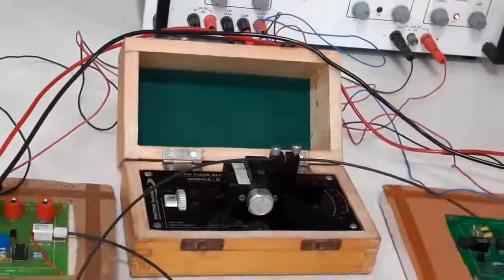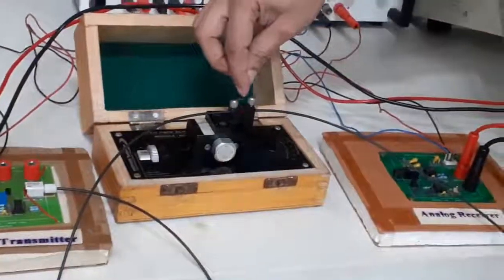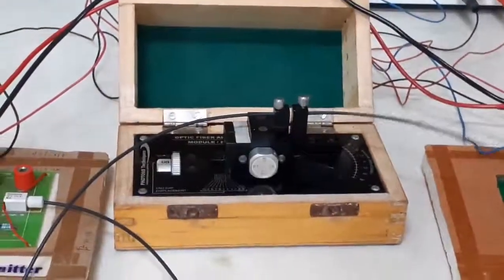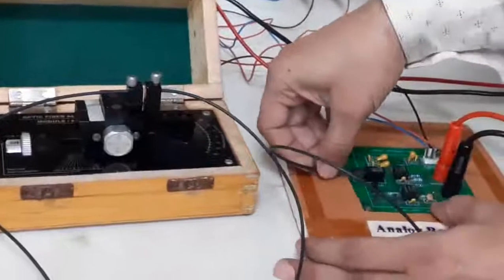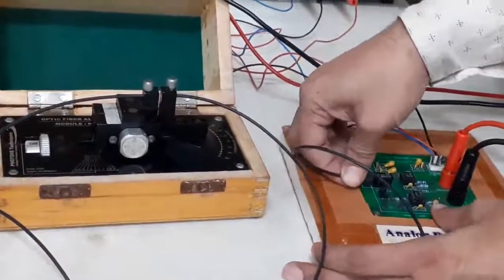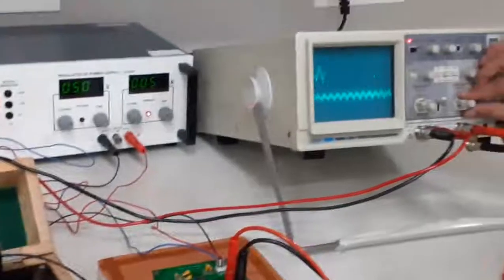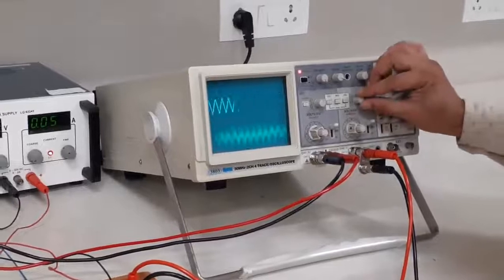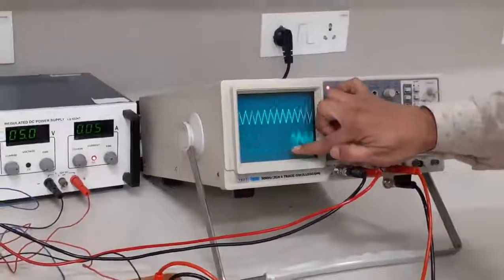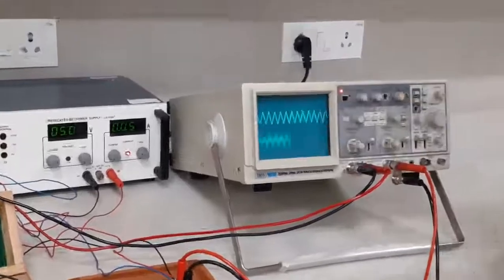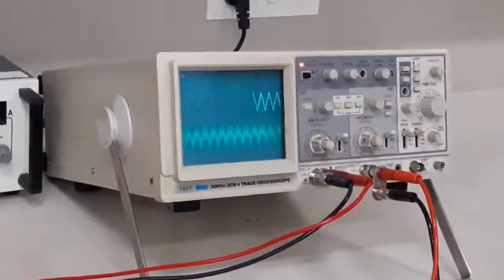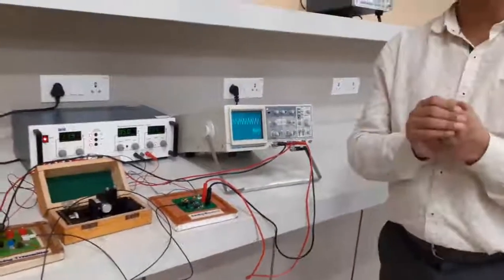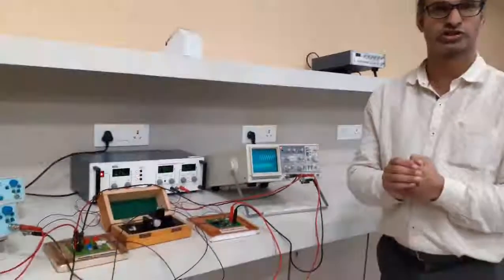Currently, this module with the default displacement between these two modules is about 3 millimeter. So the distance between these two fibers is already 3 millimeter, and so my output is decreased because I have now connected 2 meter fiber. Now my output is almost, let me adjust it, 1 division, 2 divisions and 3 divisions at about 50 millivolts. So 3 divisions multiplied by 50 millivolts, it's almost 1.5 volts peak to peak.